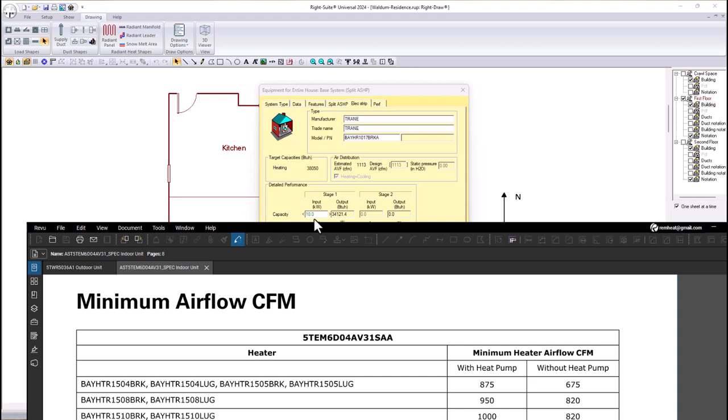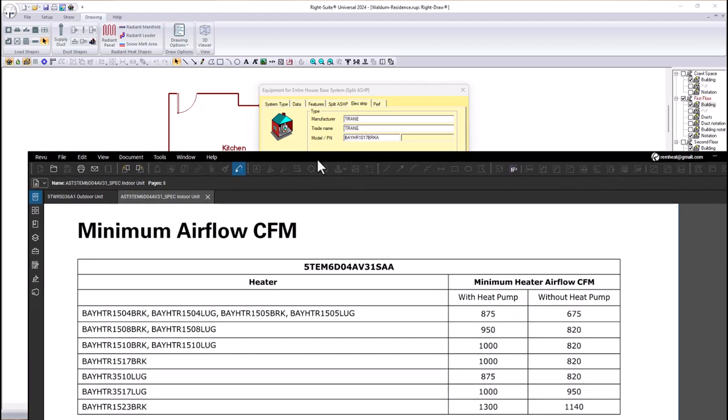So in this case, since it's the central, located in Virginia, I'm going to put 10 kilowatts, because the low ambient temperature is not going to go lower than 25 degrees. So 10 kilowatts, okay, and then we need to update this. So for 10 kilowatts, what is